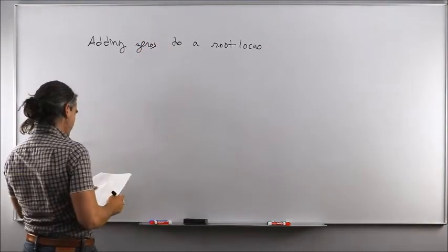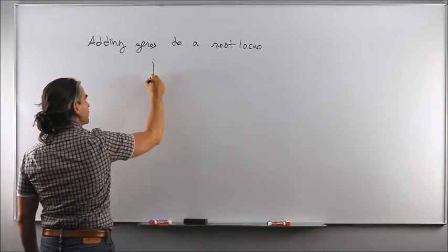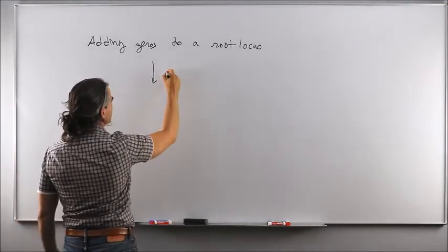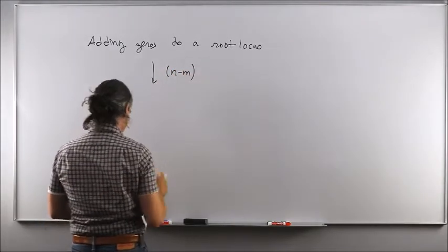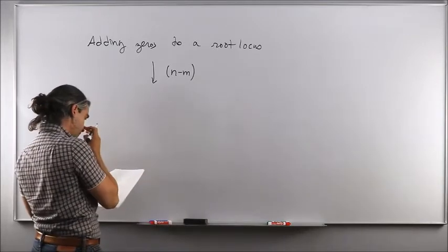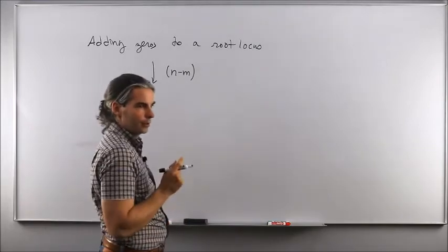to our root locus? Well, it is going to be the other way around, because if you add a 0, m increases by 1, or 2 if you add 2 zeros. So it's going to lower n minus m, therefore reducing the number of asymptotes. How is that even possible?